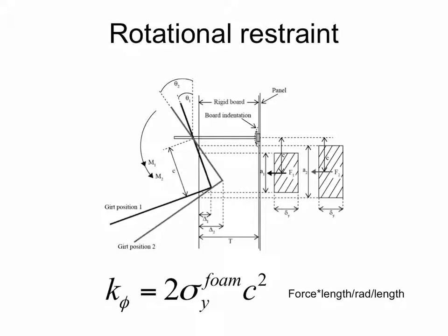So we can calculate rotational restraint including for when we have rigid board there. We can also calculate rotational restraint when we have just the bare panel. We have equations for that now too, so you'll be seeing that in 2016 as well.